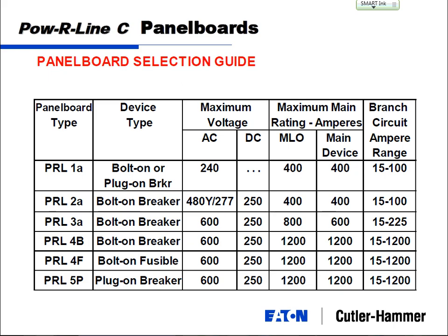This one, for solid state, the default settings might be here, but you could take that setting and say, I need to coordinate better with my upstream and my downstream equipment, so the downstream equipment trips first in the case of a fault. And I want to move this curve a little here, bend it here, and turn it up. However you need to do it to make that work.